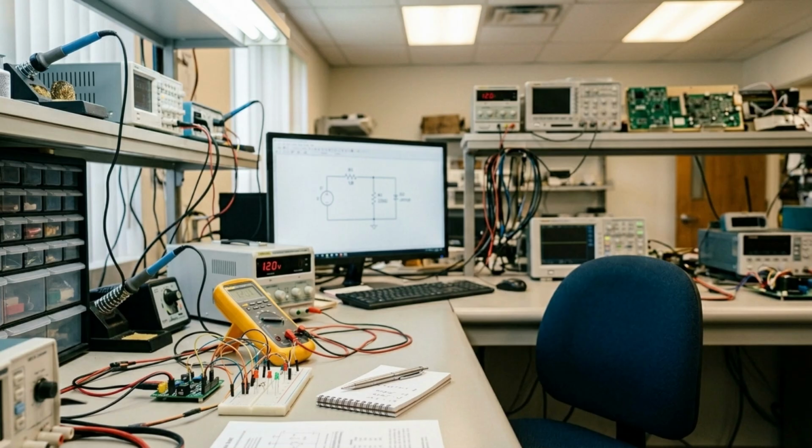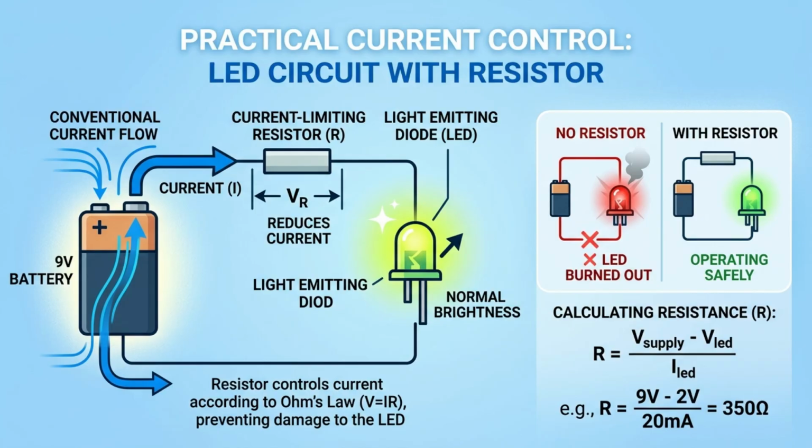It is often the first equation engineers use when analyzing a circuit. Suppose an engineer knows the supply voltage and resistor value in a circuit. Using Ohm's law, the expected current can be calculated immediately. This helps determine whether components will operate safely. Engineers also use Ohm's law when selecting resistor values, designing voltage dividers, estimating power consumption, and troubleshooting faulty circuits. For example, if a measured current differs significantly from the expected value, it may indicate a damaged component, wiring problem, or design error.